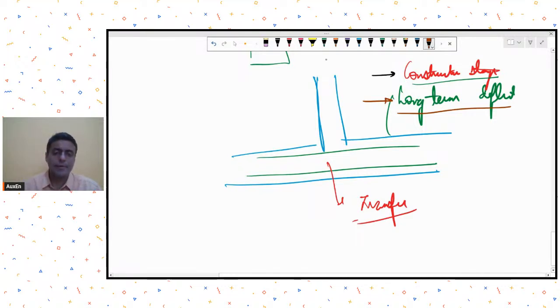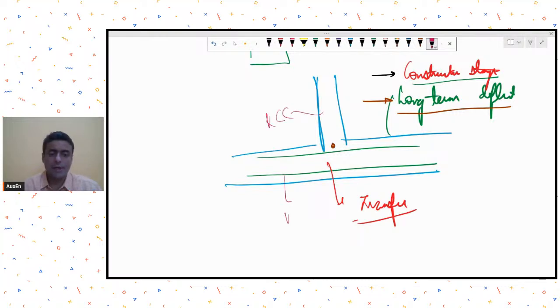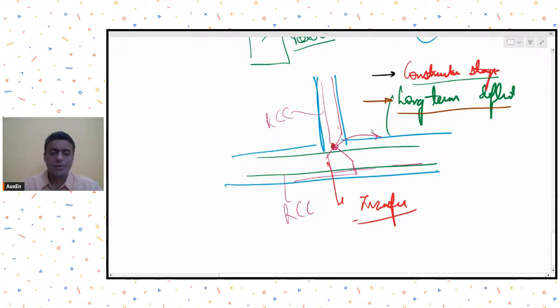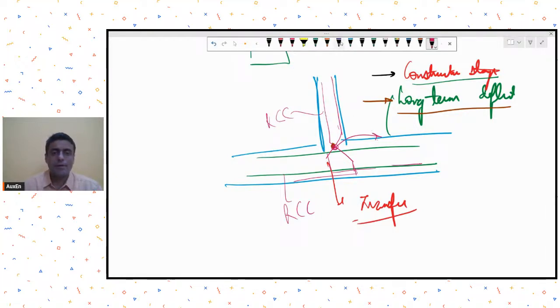Other than that, there is always this question, can this joint be a pin joint? So as long as this assembly is an RCC column and an RCC transfer girder, I'm not sure how in detailing a pin joint can be created. Although you might have seen, I have seen such details, whatever they do, that they will bend the bars like this. Although I'm not sure if it can work as a pin joint, to what extent this can work as a pin joint. So about this, I have my opinion reserved whether this can act as a pin joint.